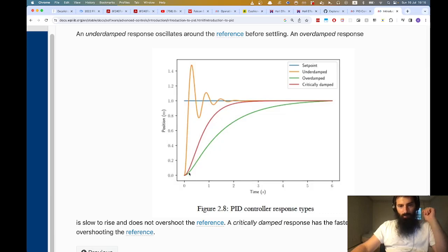Okay, so if you look at this orange graph right here, you can see that because it's so steep, it's going, let's say, at full speed, right? If it's at 0 meters, it has a long way to go. So it goes full speed, and it keeps going full speed. And then at our set point of 1, it's traveling so fast already, it has a lot of inertia. So even if you tell the motor to stop, it's going to overshoot, right? So it's going to go above 30 inches.